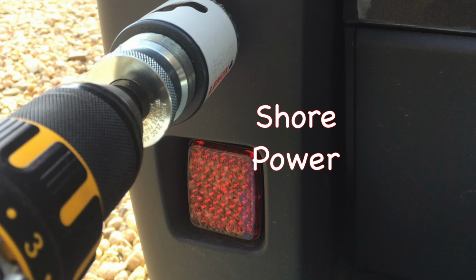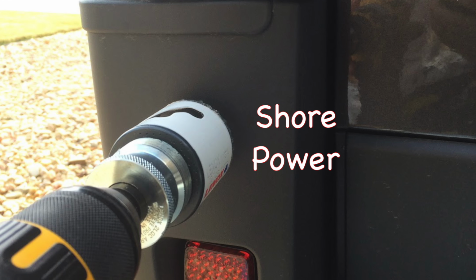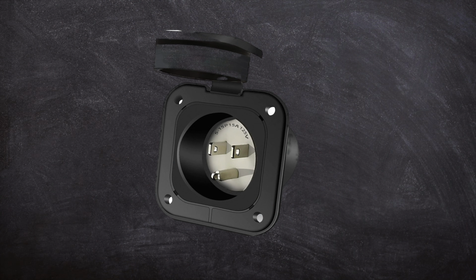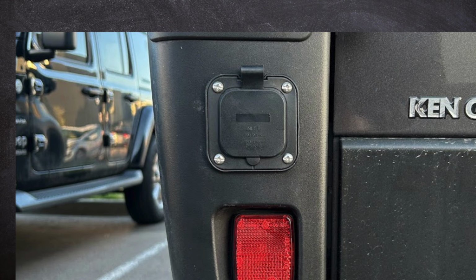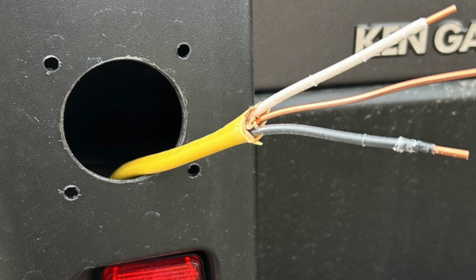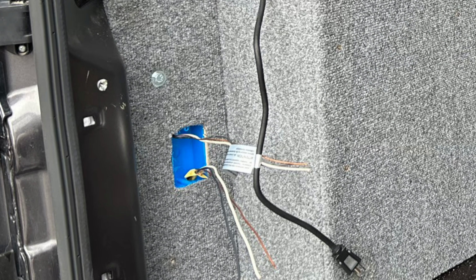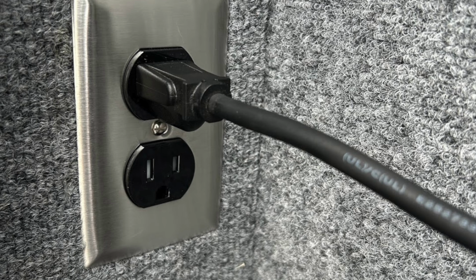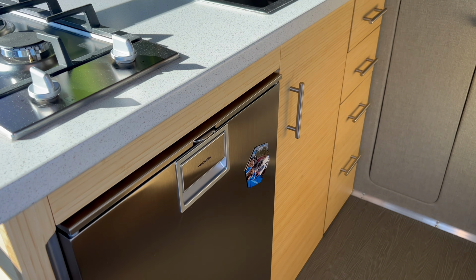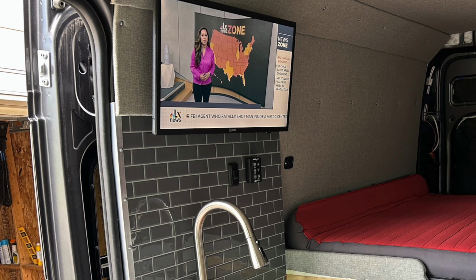Installing a shore power system has several benefits and can be quite inexpensive. A basic setup starts with a shore power outlet, which you can mount to the exterior of your van. I use 10-3 Romex household wiring to distribute this power to 3 AC outlets inside the van. One is used for the shore power charger, one for the TV, and one for the refrigerator. The TV and refrigerator automatically switch over to AC power when I plug in.